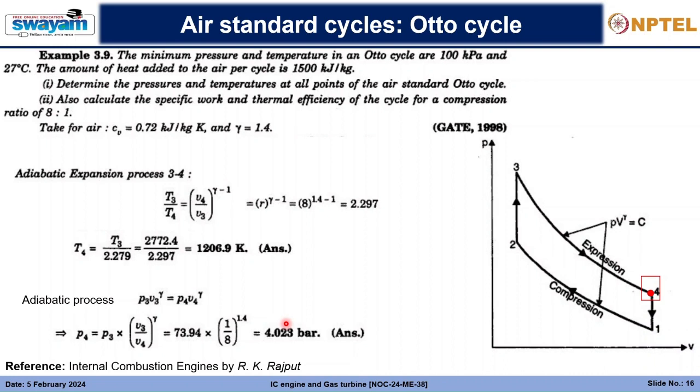Somewhere, at some point, you'll be given a hint about point 3, so this is not a normal process. The hints are given like point 1, that is the inlet condition, or the first starting condition. So the normal ambient air temperature and pressure is the value at point 1. From that we will manipulate the thermal properties of the air, and since it is not an air fuel mixture, it is simply an air cycle. Then we'll be compressing, then expanding. That will be done through the air, but the starting point is that of the ambience. So that is one hint.